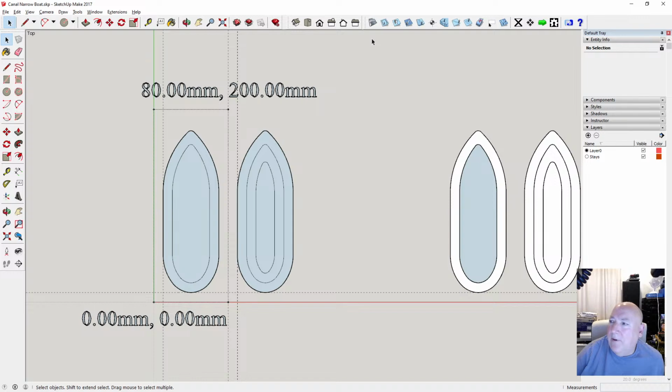So we're going to go to the pocket tool. This is where we have to work out the pocket. So we go to the pocket tool, SketchUp pocket a face. Right, it tells you if you want to override something. Shift only zigzag, control only boundary, end toggle direction, home flood fill ZZ only. Yeah, so you just get your top pocket tool, hover it over.